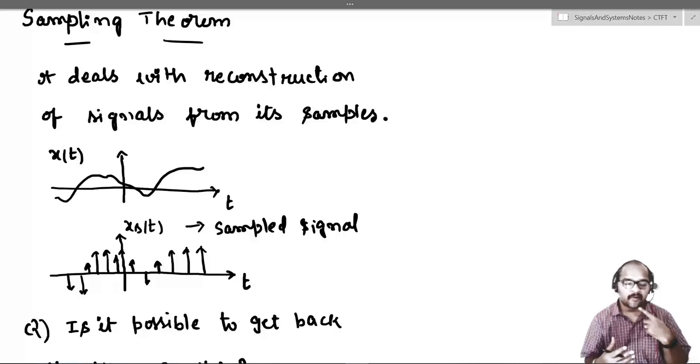For example, whatever I am speaking is stored inside a computer. How is that done? Whatever I am speaking is an analog signal. We have a transducer in this microphone, which transmits the signal, and inside the computer we store the samples of my speech signal. Because we have finite memory locations, the requirement is that our signal be sampled.